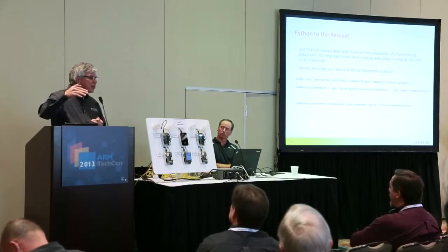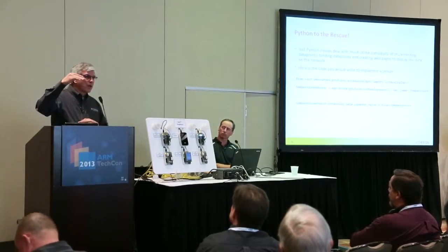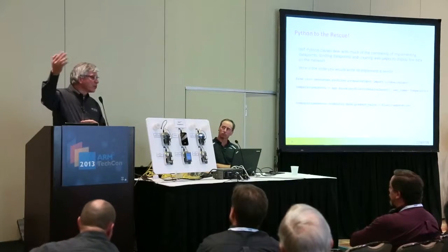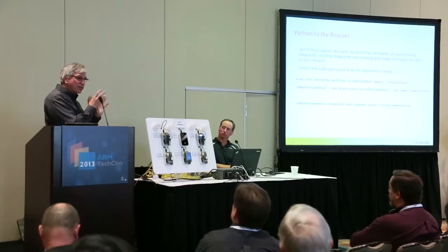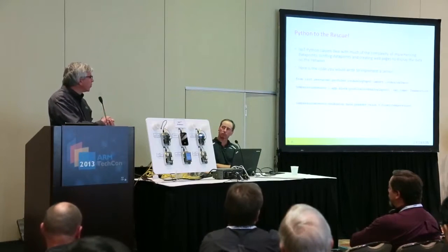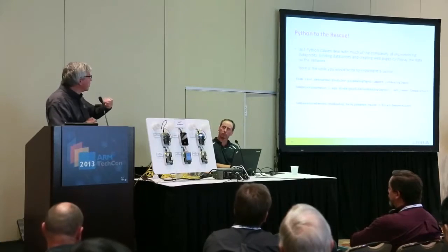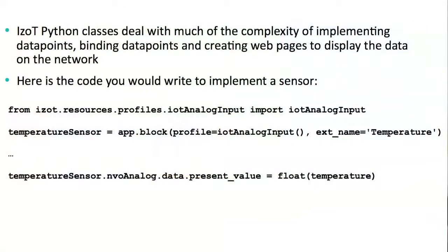If I have a temperature sensor that's sensing temperature, I want to be able to say, well, if the temperature goes over 200 degrees, that should be an alarm. So that's called a property that configures that profile, and that's defined by the profile. Right? So just by referencing the profile, which I do with that one line, I import that profile. Actually, I have that definition now available to my application, so I don't have to create all that. Right? I just have one line of code.